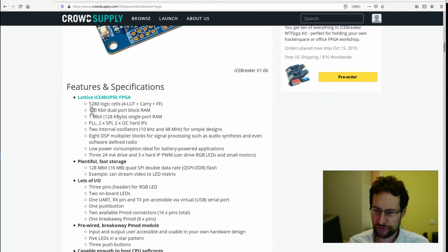So we probably want to use all of this dual port block RAM, or most of it, for the video core. This means that as a maximum we will probably only allow something like VGA 8-bit 320 by 240, which is 64K, because we also need some block RAM for other stuff, like other registers in the serial driver, the Pico RISC-V core, and so on.